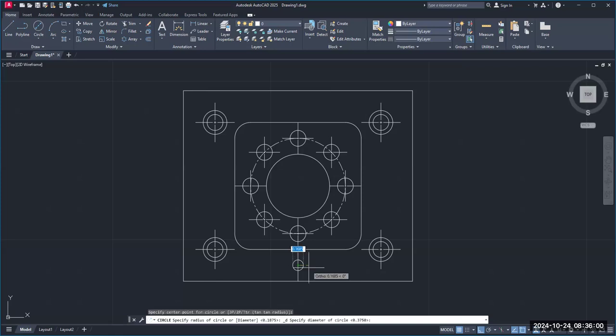Now, the major diameter for the thread call out is a threaded hole. It's a 1/4 inch diameter, 20 threads per inch, Unified National Coarse, with a classification of fit of a 2, and then B means it's an internal hole. So type in 0.25, enter.